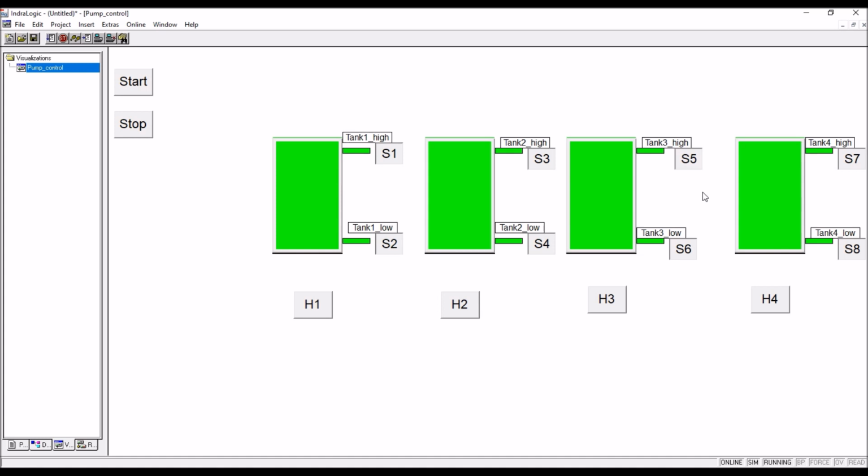Okay. Assume that I am manually draining tank 1. So what you have to do? Immediately you have to switch off S1 because it loses contact with water. As soon as it is over, we should switch off S2. Now according to the program, only one tank is empty. That load is only 3 kilowatt. It is under 10 kilowatt. Again it can be filled. Okay. Now you have to switch off the manual drain.